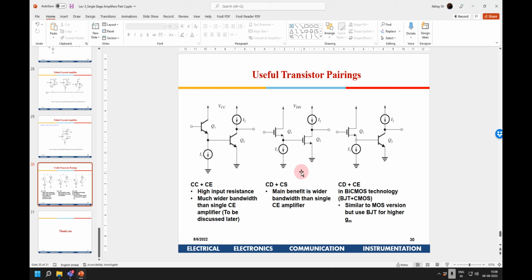So how will this benefit for high frequency? Yeah, you have a point there. At the input side, it will not have any effect, but in the intermediate stage, you will have an issue there. Probably you will have to use a cascode amplifier here or something like that. Okay, that would be the better option.